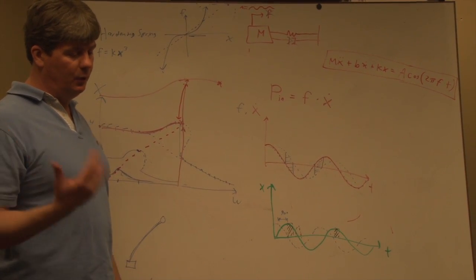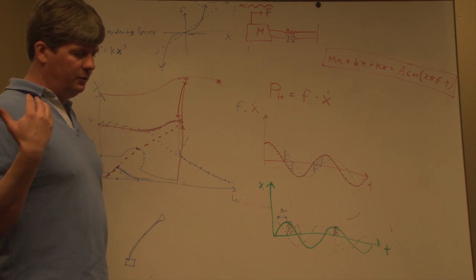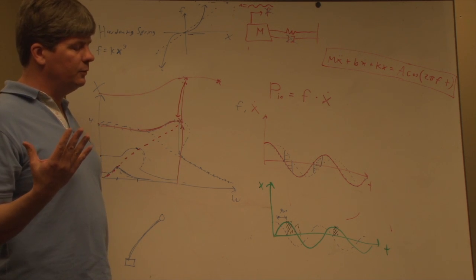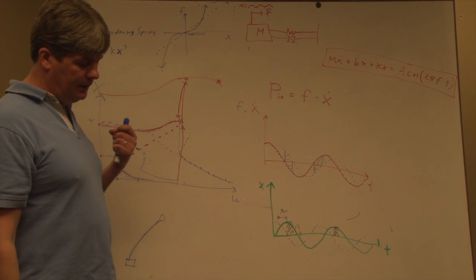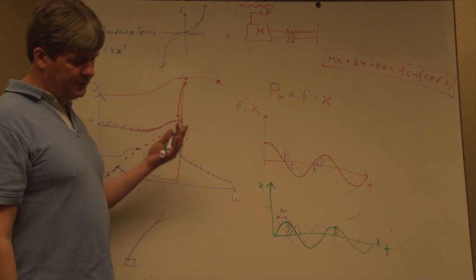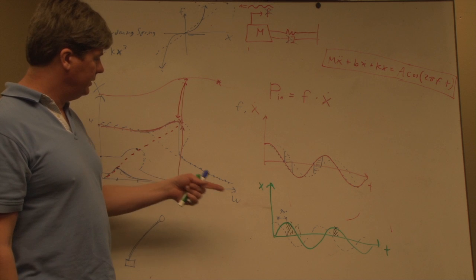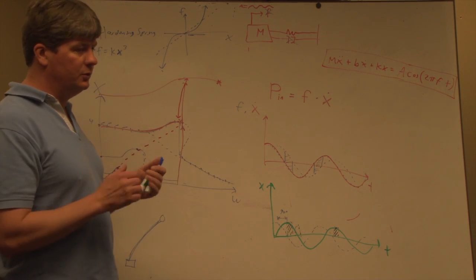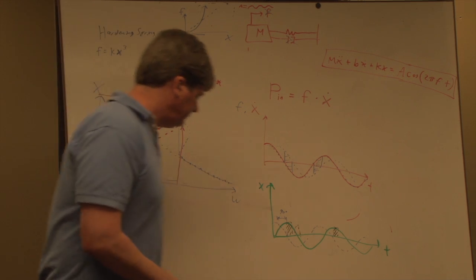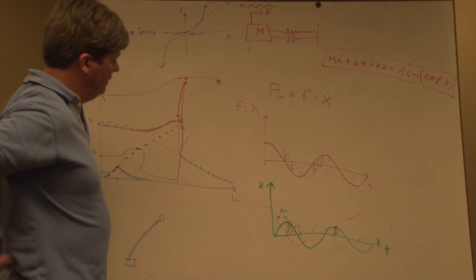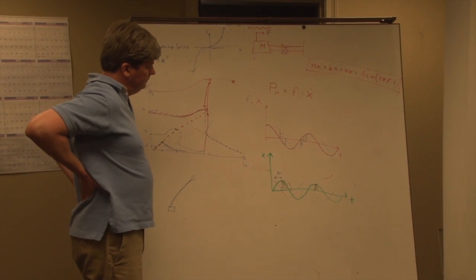For a motor that has I squared R losses, you probably want to minimize current. So there you probably want to be pushing when it's fast with low force, if you can. With a hydraulic system that has a constant pressure source, you can get pressure for free, but velocity costs you. So there you want to do what the human does pushing a swing: only push when it's at low velocity, but with large force. Ideally, you would push right along with the velocity. If it's going fast, you push harder.